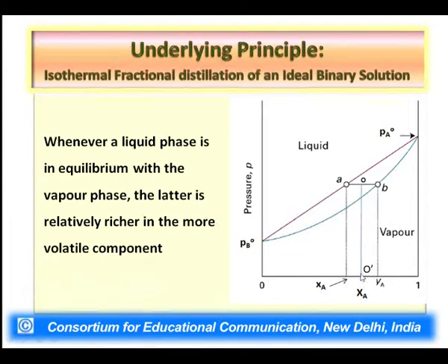If we raise the pressure on the system by decreasing the volume of the system, then the pressure of the system will increase, because the same amount of the gas mixture, when subjected to lower volume, will have its pressure raised. So, upon increase in pressure, the overall state point of the system will continuously move upward on this blue vertical line.